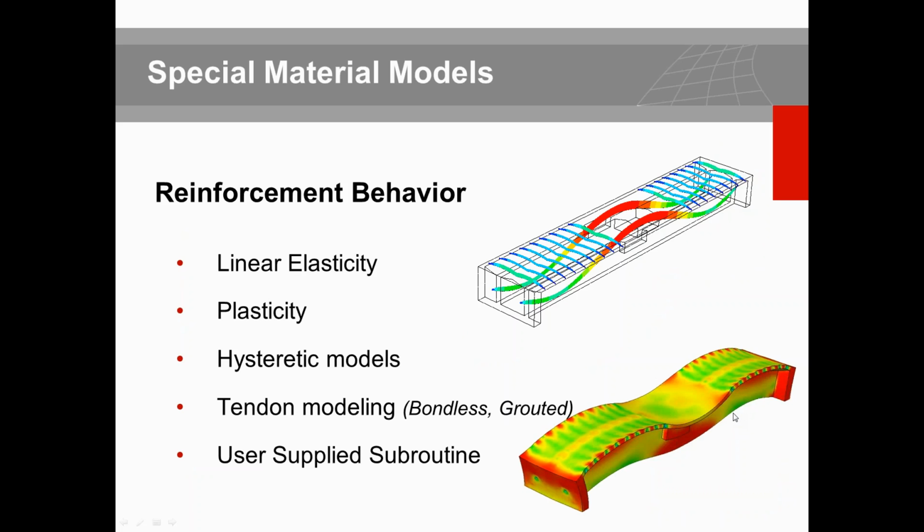For reinforcement and bars and cables or tendons, we have different characteristics. This could be linear elasticity, plasticity, or hysteretic models to capture these energy-dependent material behaviors. And for tendons, you may consider the grouting and no-grouting effect.